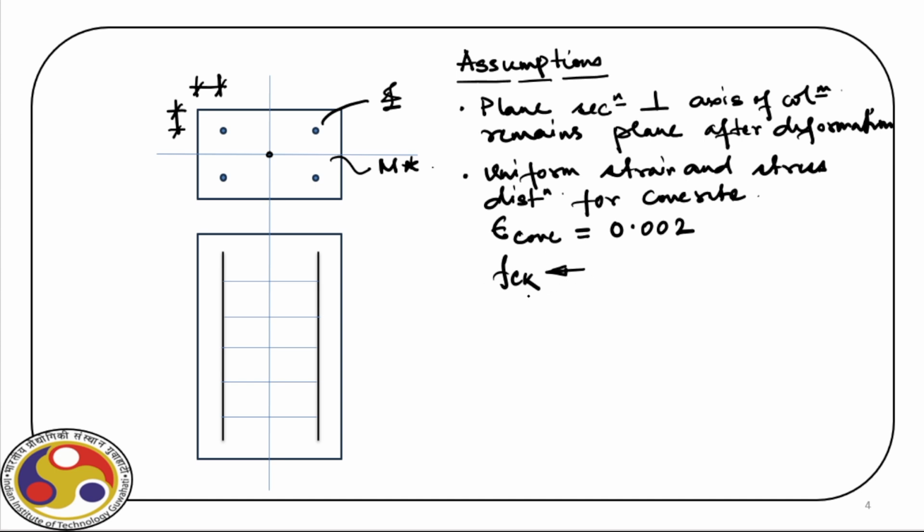Now, we get this fck from the cube test, and therefore the stress in concrete is 0.67 fck, as we did in case of beam design, and then factor 1.5.